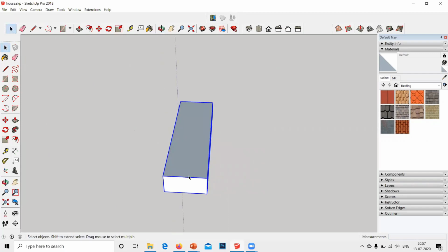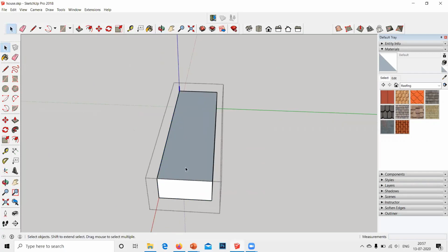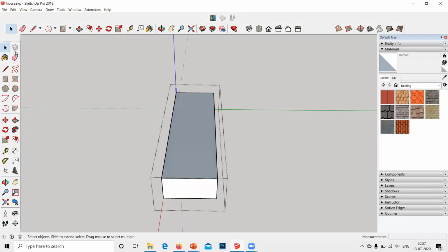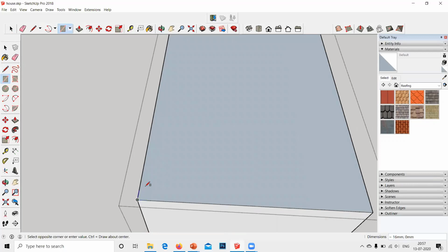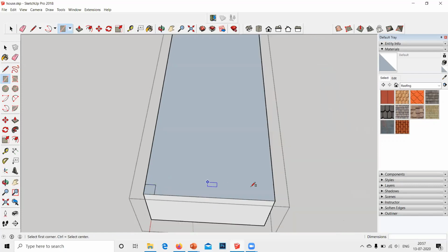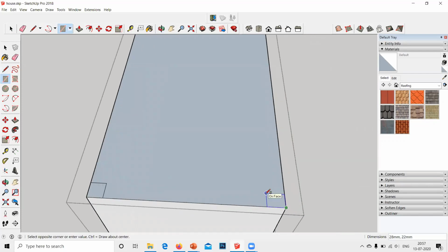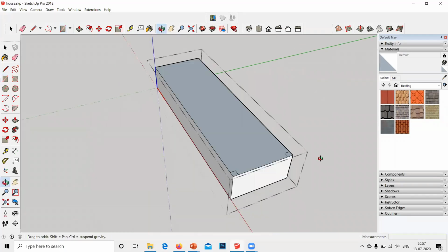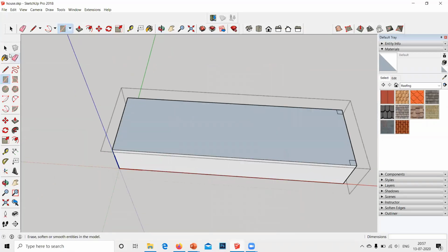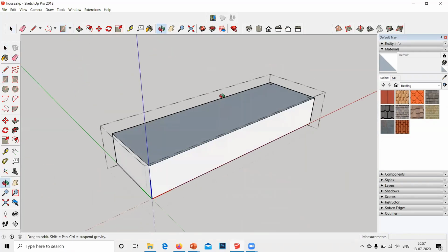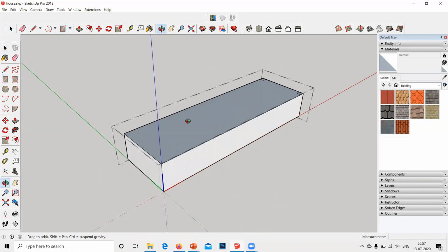Okay, now I want a railing here only. I'll just make this component unique because I'll do some small modifications on this component. I'll click on make unique. Once I make this component unique, all my changes will not be reflected on these stairs. Okay, so it's important for me to make this 25, 25. Enter this component. Okay, so now I'm just going to delete here. I don't think we should delete this here because we are anyways going to flush this staircase on a wall. Erase it.